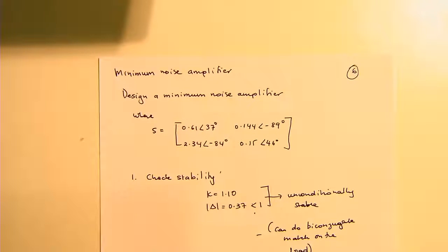And one of the things that I did say, and it's just a little bit of interesting information, if you've got the equivalent temperature, that also means that if you cool that device down, you can also reduce its equivalent noise temperature, so therefore you can actually decrease its noise figure. So that's another thing that you've got up your sleeve if you really needed to reduce the noise figure of a device, right? Anyway, as an aside, I always find these things exciting. Hopefully you all do also.